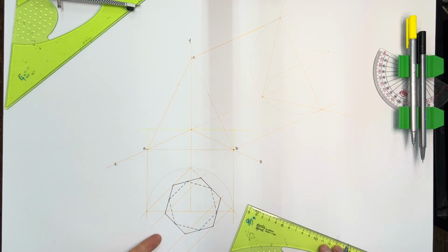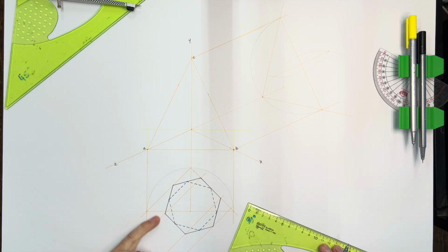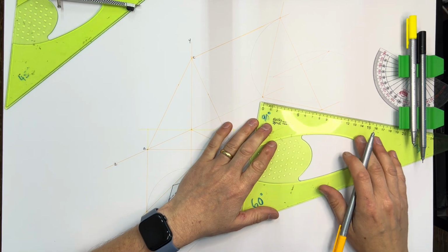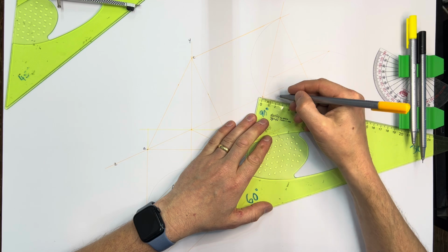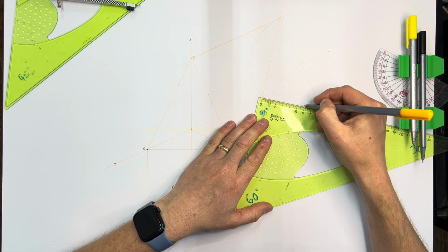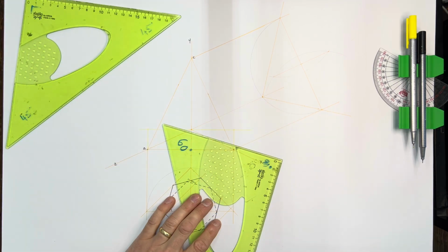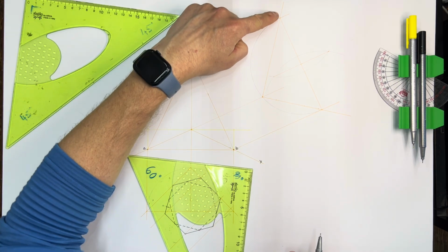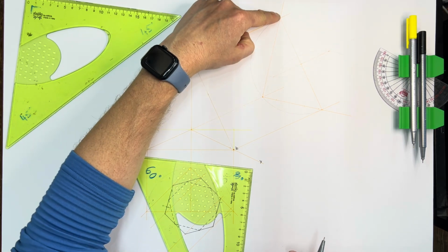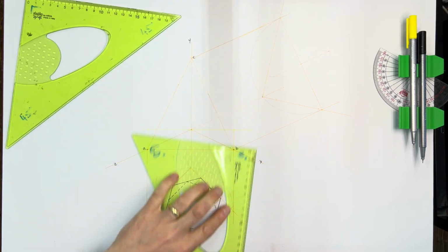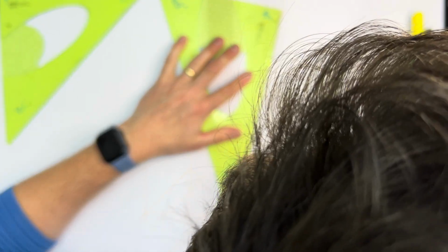All right, so as we're looking in from the left here, we know that this hexagon was dimensioned 20, 40, 20. So I'm going to see the same 20 mil section here, 40 mil section here, 20 mil section there. So they're the dimensions I'm going to apply here in the elevation. So 20, 40, 20. The heights: we're given the overall height, which is at this point here, and we're told to measure up 20 and down 20. So I'm just going to do that now so as I can take all the points at the same time. So down 20 from the top and up 20 from the bottom.